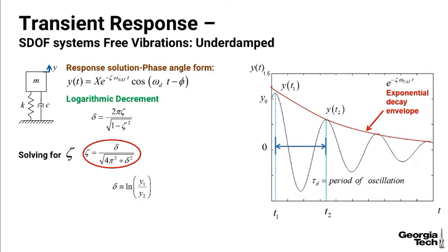And so, as I said, I have the definition of the logarithmic decrement. It's very hard to measure, particularly in vibration systems that are oscillating very quickly, the successive amplitude of the first peak and the second peak. So if you use multiple cycles, you just use delta equals 1 over n times the natural log of that first peak divided by the y n plus 1 peak.